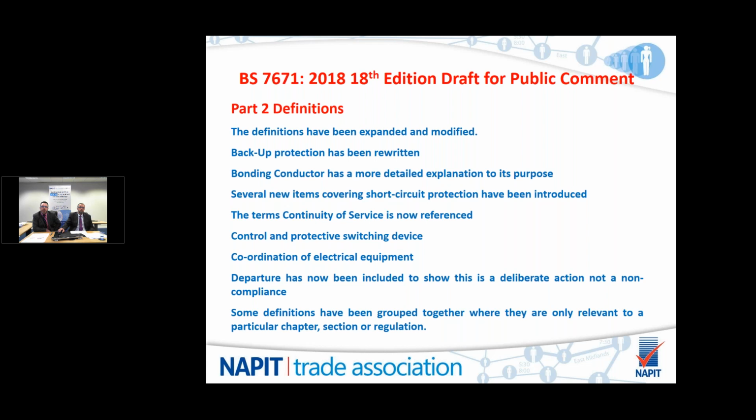So a designer might include something that doesn't yet have a product standard, but this is put down as a departure, and the details of that departure must be included within the electrical certification and any relevant design sheets, explaining why it's been included. Departure is not a non-compliance.